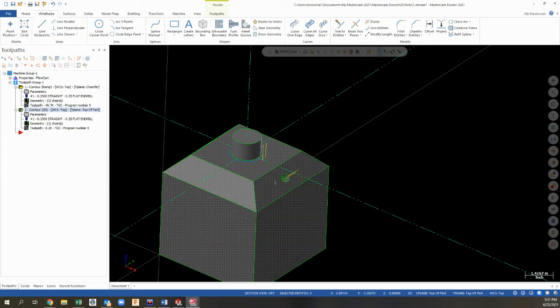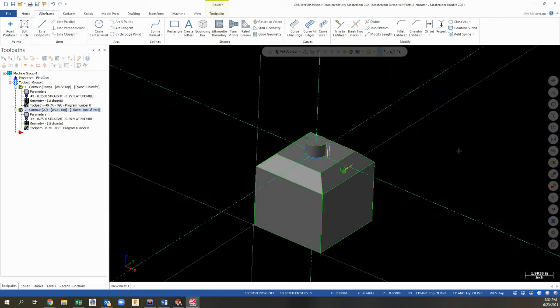All right. 9 out of 10 times our tool plane and our construction plane will be the same. There are instances, very specific instances, where they may be slightly different. If we have a tool path and we copy the tool path and want to array or rotate, kind of like a theta of our tool paths, but that's something else we won't discuss now.